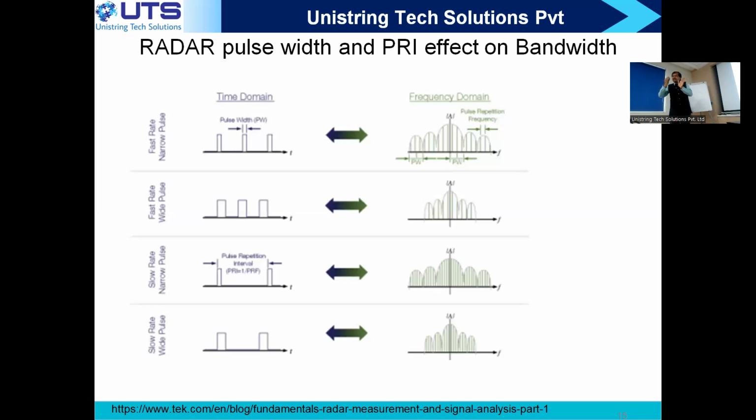So if you're able to make the pulse smaller and smaller in the time domain, I'm going to get a finer, better range resolution. But when you make the pulse smaller and smaller, its bandwidth increases. Isn't it? You may ask, sir, what is the challenge in bandwidth increasing? In digital signal processing implementation, one implementation challenge once the bandwidth increases is straightforward. If the bandwidth is increasing, it obviously means your sampling rate increases. You know the Nyquist theorem and all.